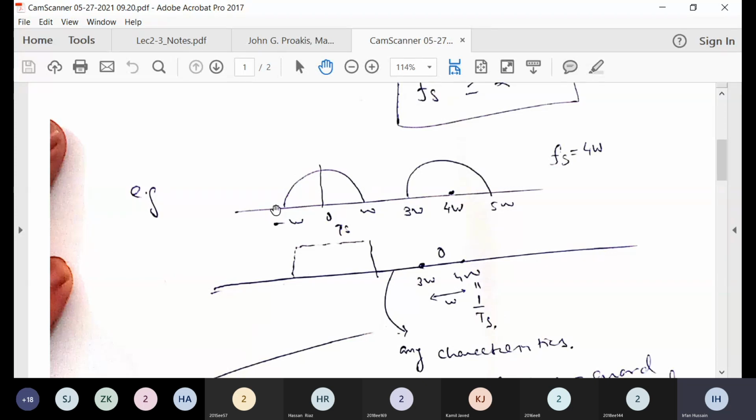You just take the signal around this from the spectrum, and the baseband, original message signal is taken out by the reconstruction low pass filter. All the replicas vanish, and you get back the original signal.